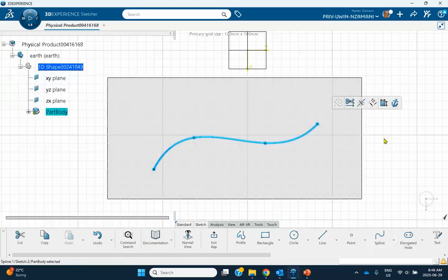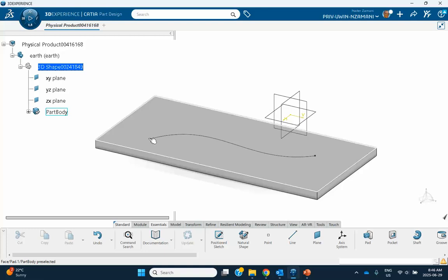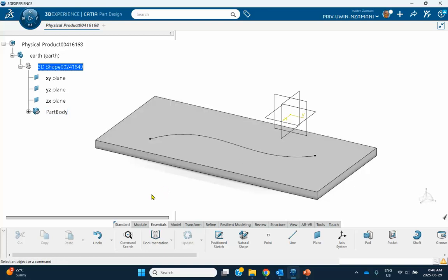Now, when you look at tutorials 9 and 10, you'll see that I have created a plane here perpendicular to that path. That is the reason I did that. I wanted to position the axis so it's tangent to that path. It's just that in the CATIA program, it had to be tangent, otherwise you cannot create a roll curve joint.